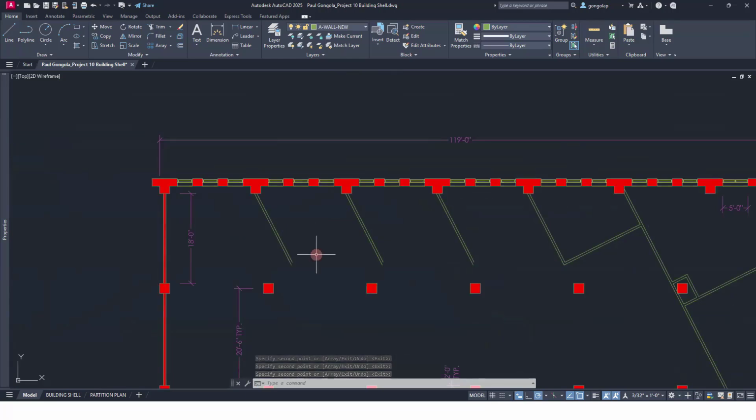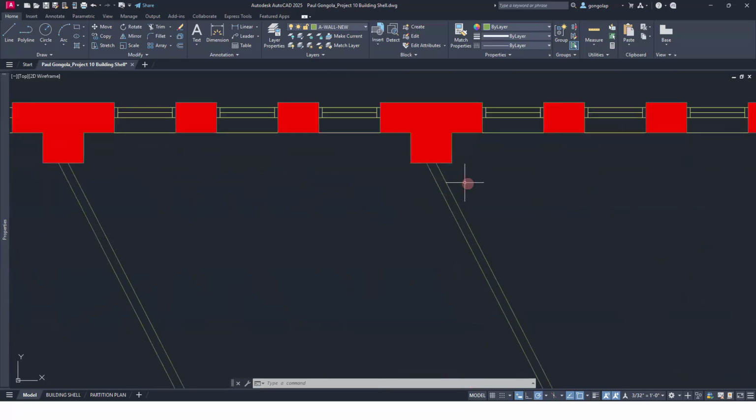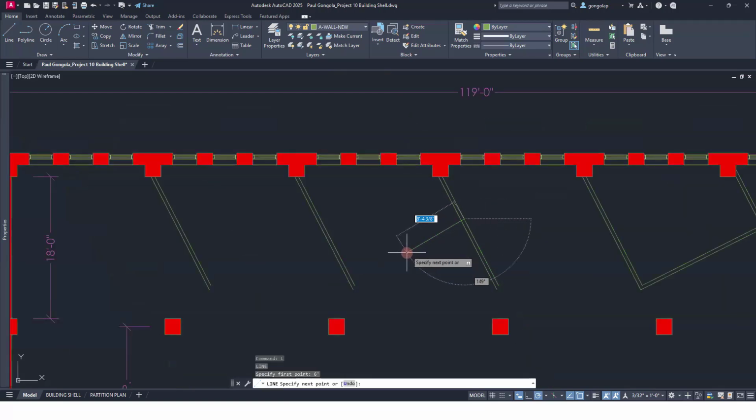Beautiful. All right, so now let's get this office, and there's a little 6 foot. This wall here is only 6 feet long. So let's O-track down along here 6 feet, and then go perpendicular to that wall, and I'll offset 5 inches.